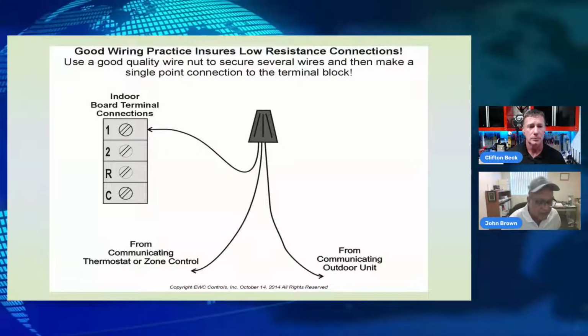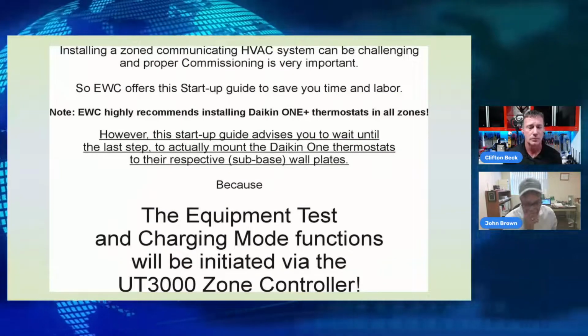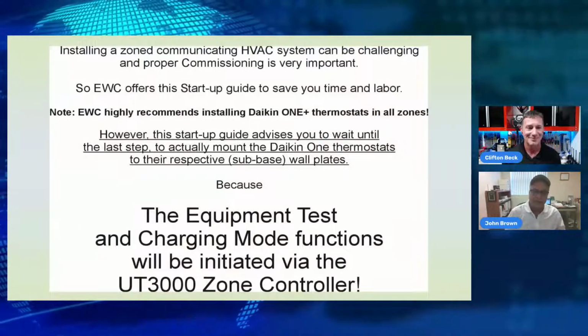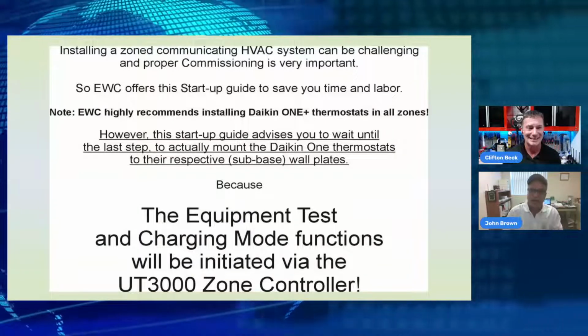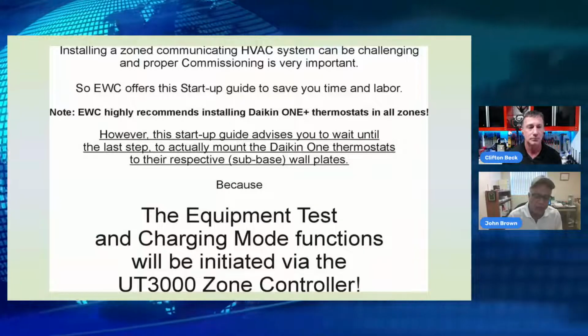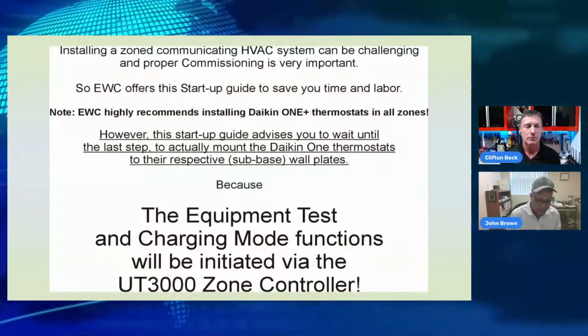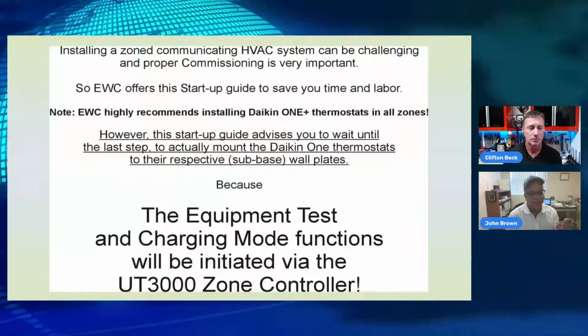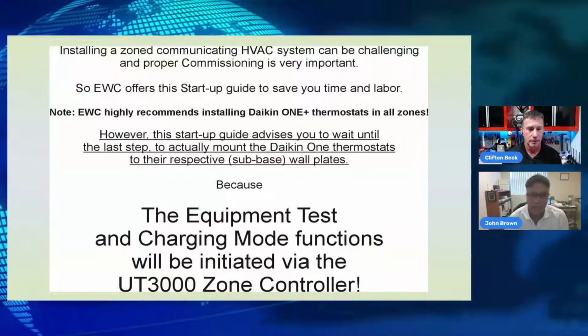You're exactly right, Clifton. I ran into this on a job. Believe it or not, I got a call from Hawaii. Well, this guy's splice connection from the indoor to the outdoor was so corroded, it simply would not communicate with the outdoor unit. It took him a while to find it, but he did, cleaned it up, and it worked like a charm. Thanks for pointing that out.